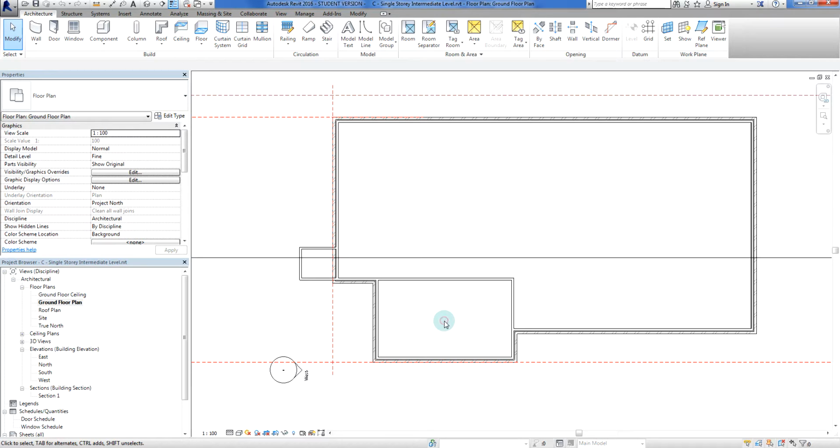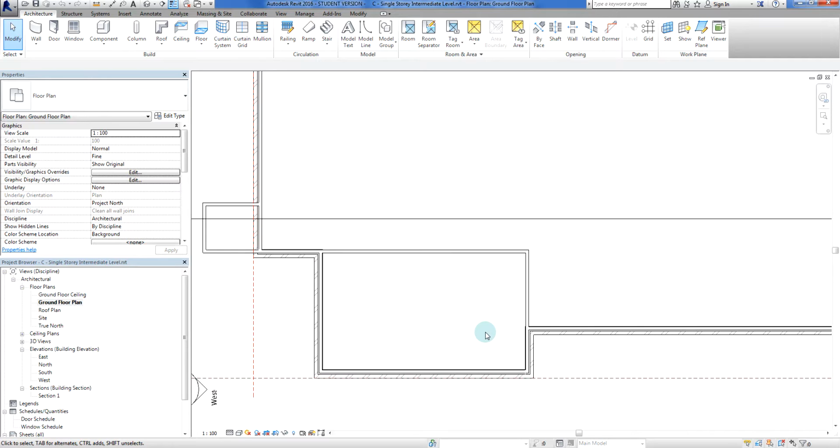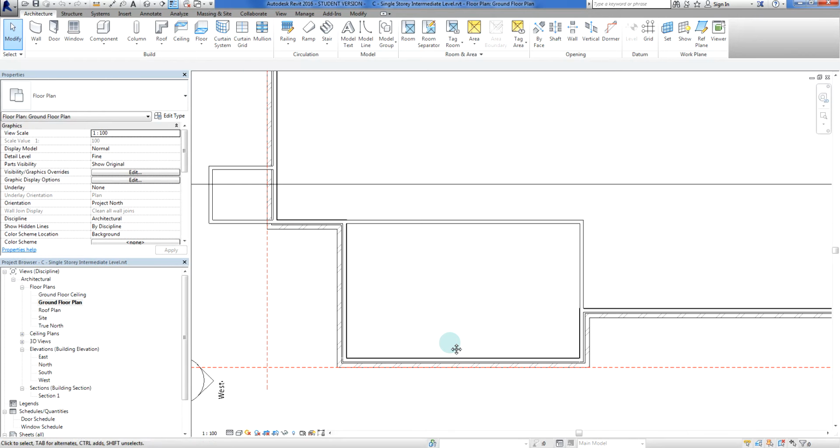Okay, so let's have a look at one of the ways we could do that without upsetting the rest of the design, of which luckily enough we don't have. The key thing here is that in Australia, if we're to do a double garage, the general rule of thumb for the minimum internal dimensions is 5.5 meters across and 6 meters internal.